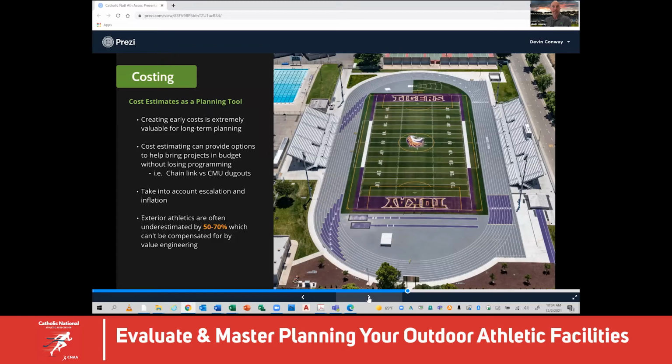Well, that is for general engineering and general building construction. These athletic facilities are kind of a world unto themselves. If you don't understand everything that goes into a turf field and the specific base materials that go under the turf and the pads and the complexity of the asphalt for a running track and the tolerances of that, it's not a parking lot. You can't use that square footage price for a track asphalt because it won't pencil out when you get the bid.